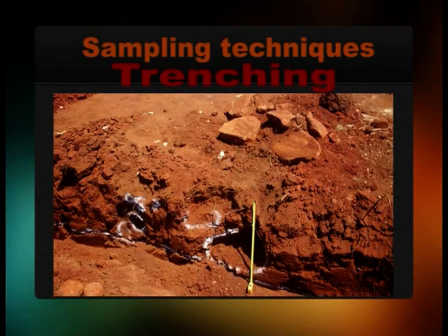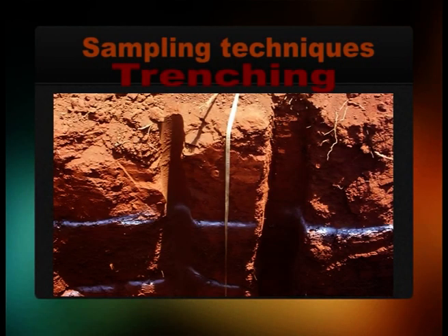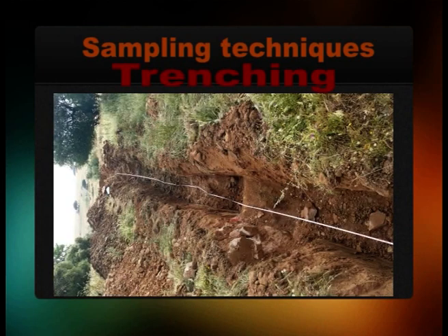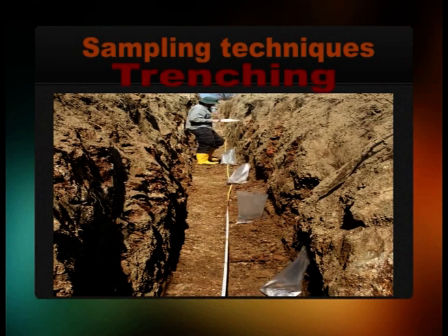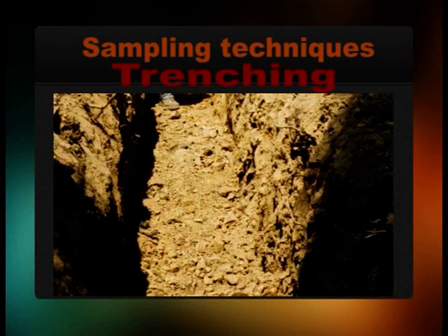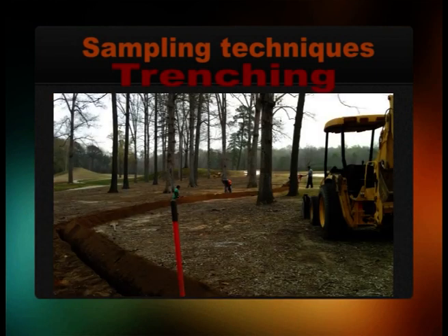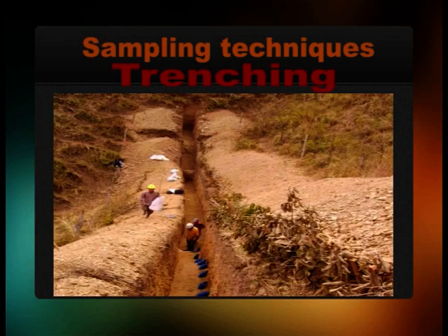Now coming to trenching. Trenching is usually completed at right angles to the general strike to test and sample over long lengths, as across a mineralized zone. Excavation can be either by hand, mechanical digger or by bulldozer on sloping ground. Excavated depths of up to 4 meters are common.